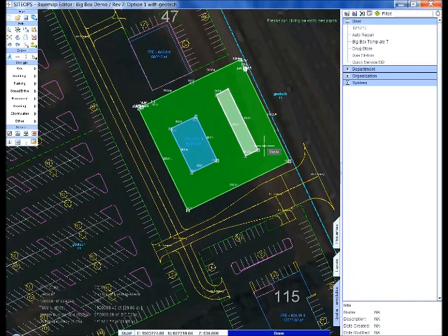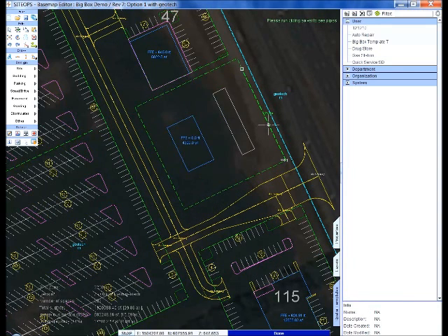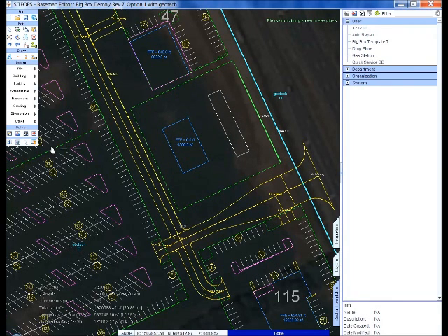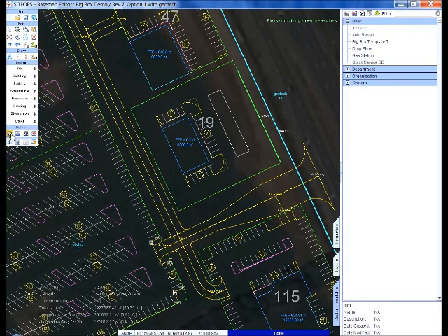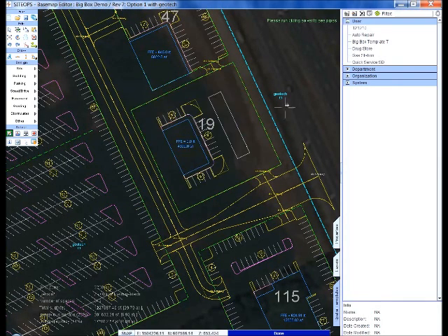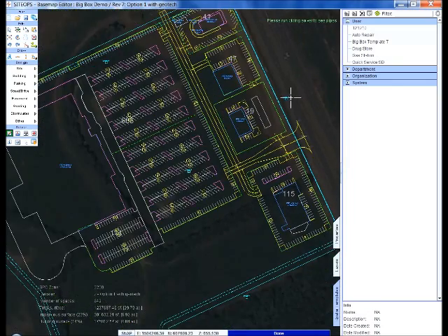Bring this gas station up. All I got to do now, simply come in, do a quick offset. Maybe again, I want to align this up to a property line. Drop a few driveways, hit the solver button, and I'm done. By use of templates, you can make your life even simpler and even faster than SiteOps already does if you don't use them. So there we go, that quick I've created a gas station.